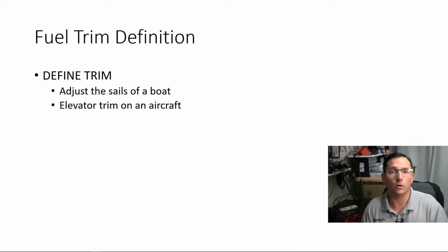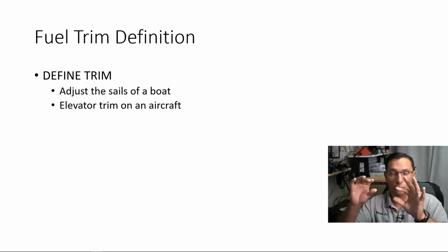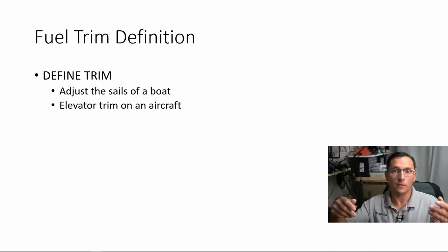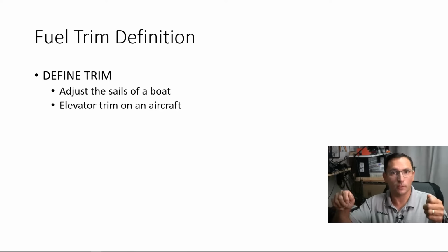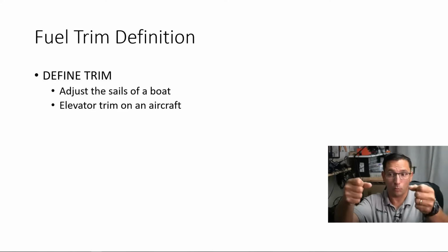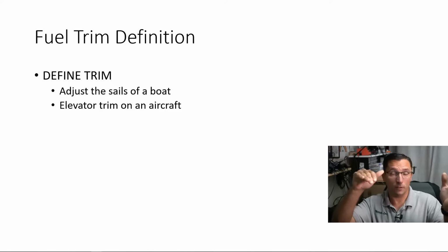What about when we're talking about elevator trim on an aircraft? If you've ever played a flight simulator video game where you have to fly an airplane, if it's not a true toy game, if it's an actual real simulator, you're going to find, depending on the airspeed of the aircraft and the pitch that you want to maintain and the power level and all these other inputs, you have to adjust the trim. On a little Cessna, it's a little wheel you spin up or down to adjust the trim, so you get to the point where you can let go of the control yoke or the stick of the aircraft and the aircraft will fly straight. I almost said vehicle, right? The aircraft will fly straight and level if you let go of the control stick. And that is trimmed.